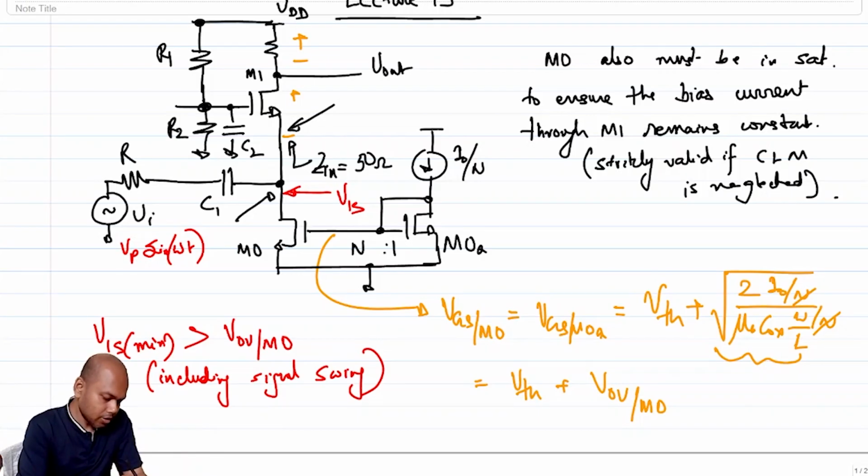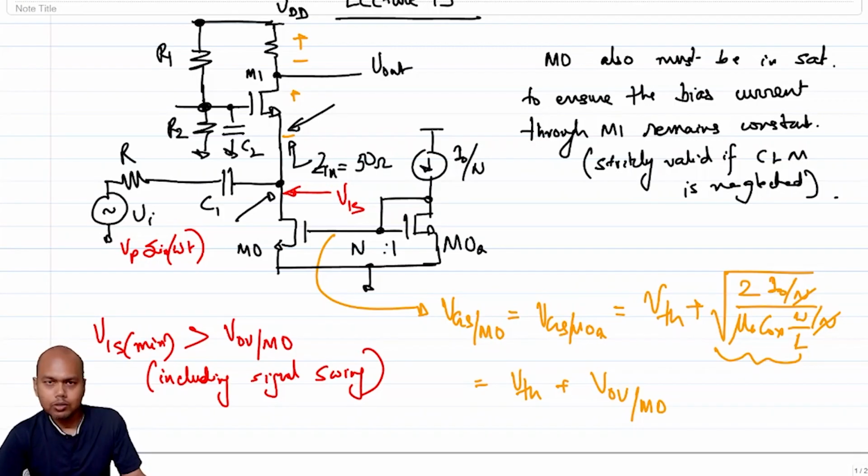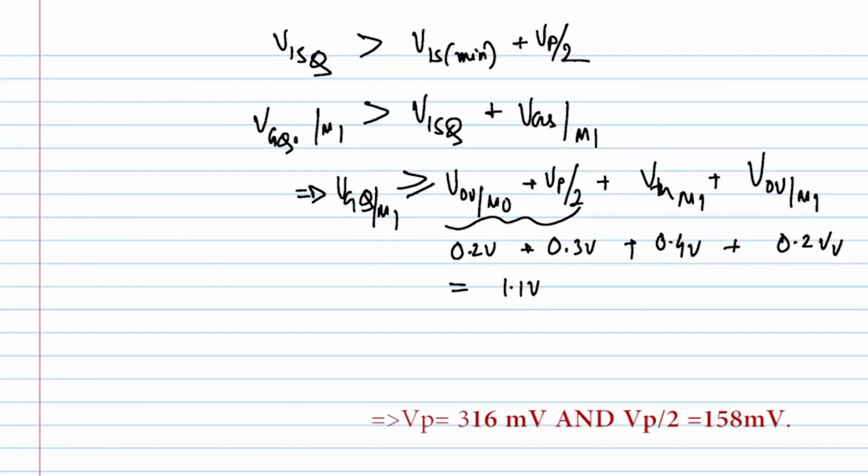So what's the solution? The good thing about designing circuits for RF is we can use an element which we normally tend not to use in analog circuits, and that element is an inductor. And why is it a good thing? The good thing is because the impedance of an inductor goes up with frequency, right? So we can then start using inductors to mimic an open circuit if the value of the inductor and the frequency of interest is above a certain value, right? Okay.